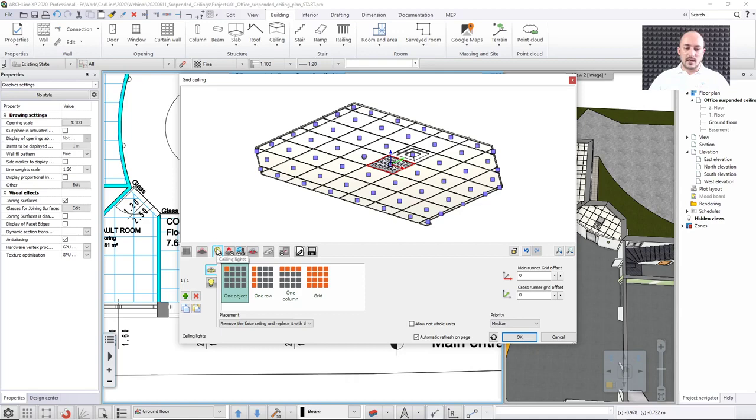Now, if you go to the first page, I mean the first out of these 4, that is the ceiling lights. Now the ceiling lights, and each and every one will have the same setting here, has the first page for the distribution system. Now, if you go with the 1 object, 1 row, 1 column grid setting, it will have a completely different layout. By default, if I remember clearly, if you just kickstart with an empty new project, this will be the default that you can see on screen, not this one that this project has as the default. So this is what you will see for the first time, and you can customize the grid steps, as you can see, this way and this way, and then also you can just type these values.